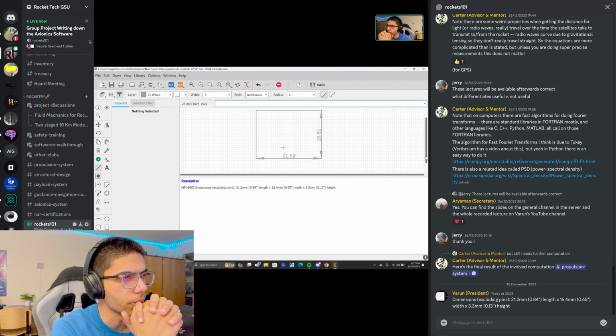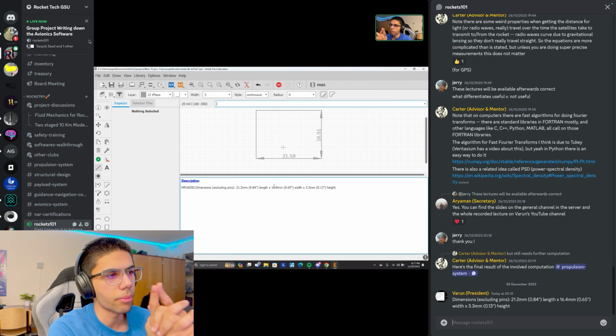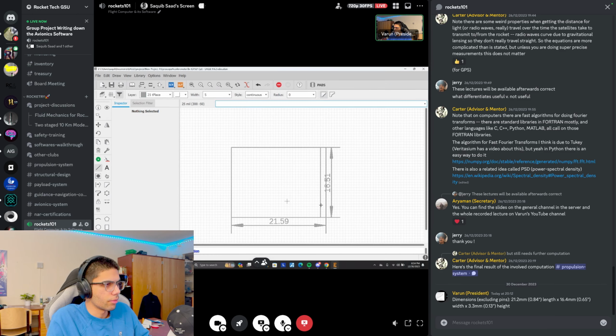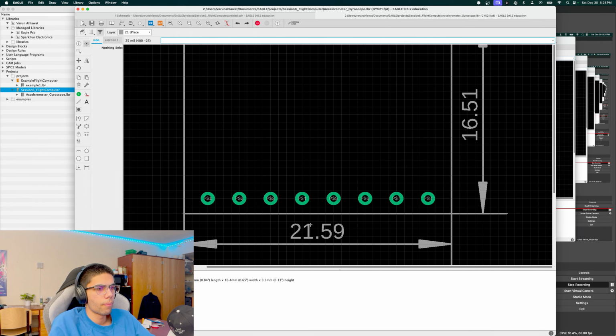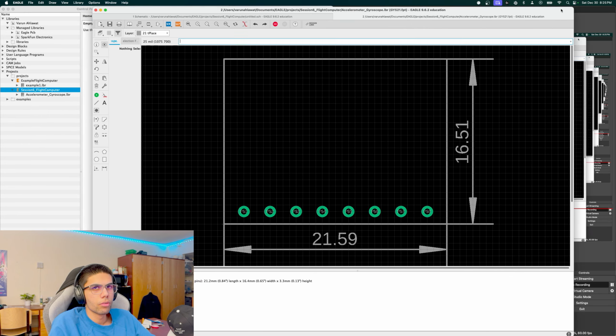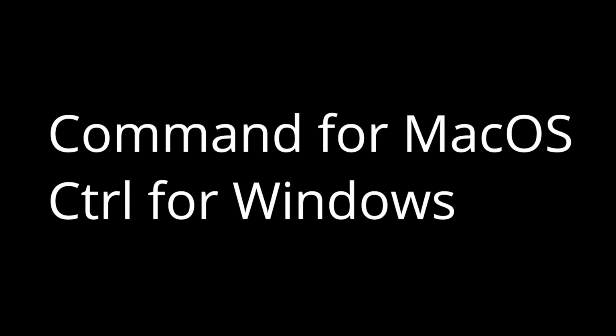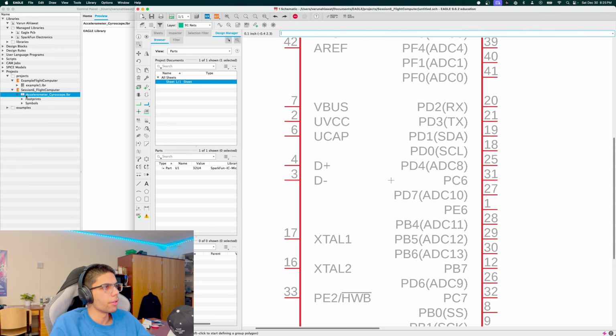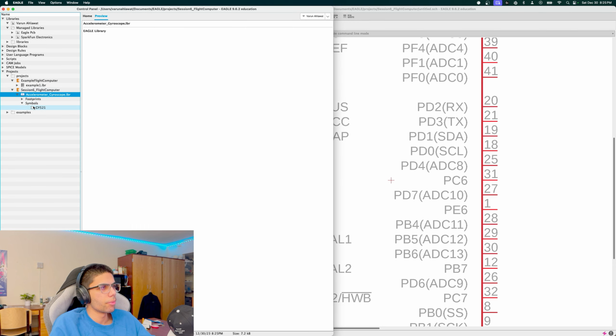Your rectangle is not complete. These are just the arrows, not real lines. Now just click on the pads, the green option in the toolbar, and place these pads symmetrically. Okay, so now we're gonna save it. Hit Command S. Now you can just close this, and saved, you'll be able to see your footprint.